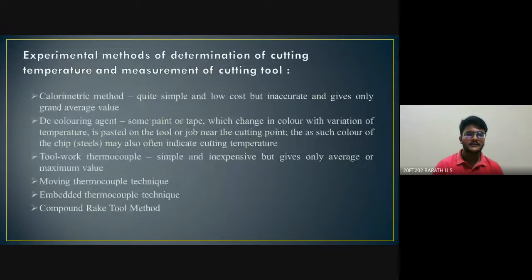The next question is how do we measure the cutting temperature. Different types of methods are used. The calorimetric method is quick, simple, and low cost, but it is inaccurate. It gives only a gradual average value in this method.